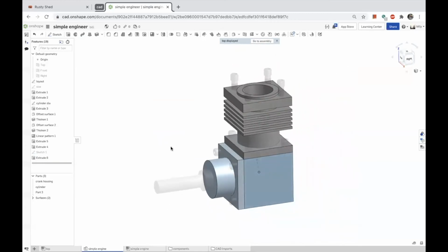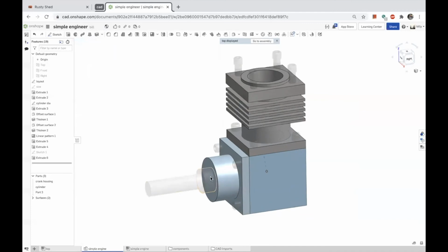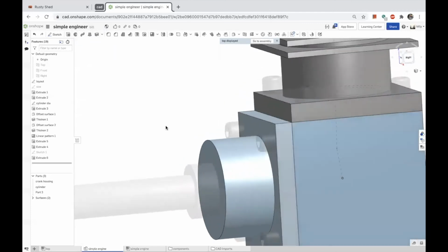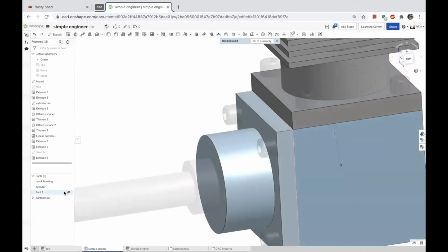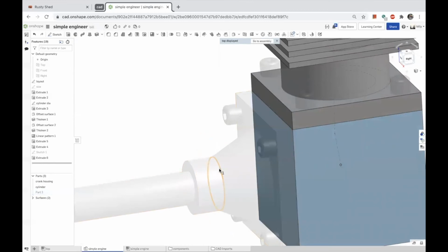All right. So the other thing that we can do, since it appears that this was originally drawn in inches, let's just go off and change our units to inches and see if this gets cleaned up. All right, so now if I want to know what the distance is from here to here, okay, who knows what dimensions these were in?